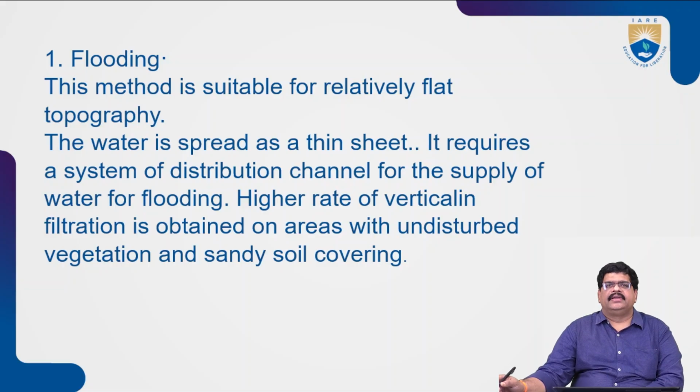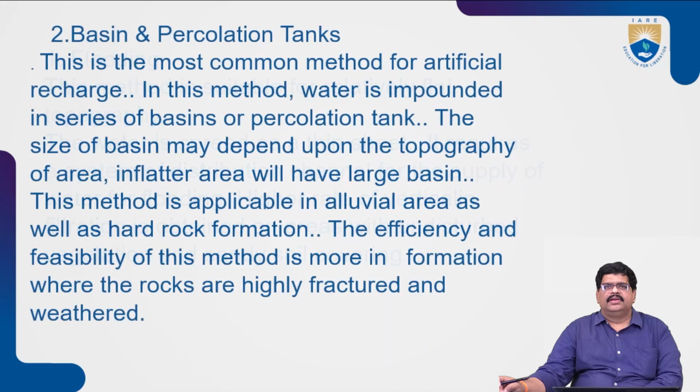Next, flooding. Flooding is most suitable for relatively flat topography. The water can be spread as thin sheets. It requires a system of distribution channels to support the water flooding. A higher rate of infiltration is obtained on areas of undisturbed vegetation and sandy soil coverings. So this is the flooding type of basin.